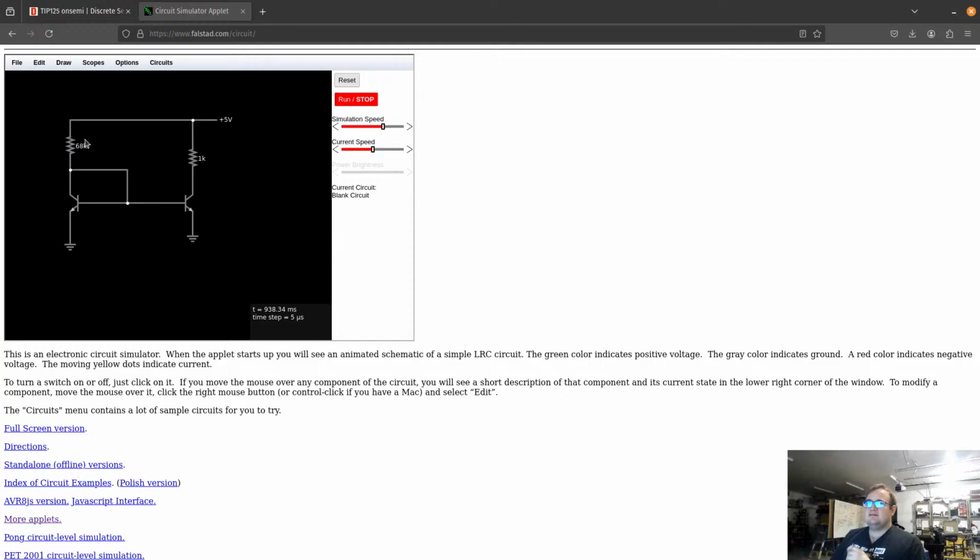When we do that, a certain amount of current, actually I'm going to make this better for easier math here. Say 50K. 5 divided by 50K is 0.1 milliamps, so about 100 microamps. It's going to flow through here and into these bases, or part of it will flow into the bases. What it's going to do, for our purposes, is that actually only 100 microamps will flow through here.